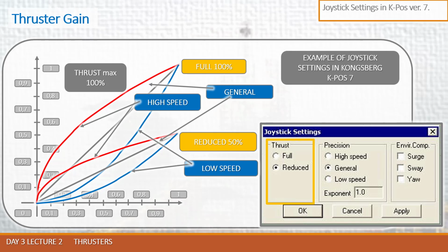The deviations in position, speed, heading and rotation rate are multiplied by the selected gain factor to obtain the required force set point. The most suitable gain level depends on the vessel characteristic, the weather conditions and the required position accuracy.